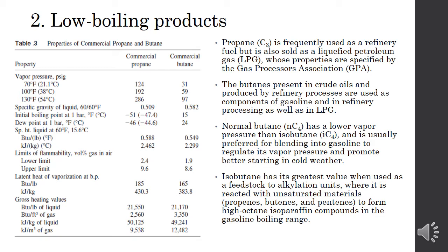The first was the increased availability of N-butane during the summer months, and the second was the necessity to provide another method of providing the pool octane lost by the removal of the excessive N-butane. N-butane has a blending octane in the 90s and is a low-cost octane improver in gasoline.